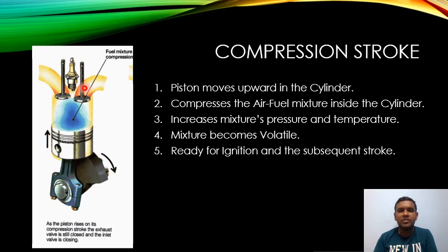This increases the mixture's pressure and temperature. When there is compression, pressure automatically increases, and where there is high pressure, there is high temperature, as both are proportional to each other. Here, the mixture becomes volatile and gets ready for ignition and the subsequent stroke.